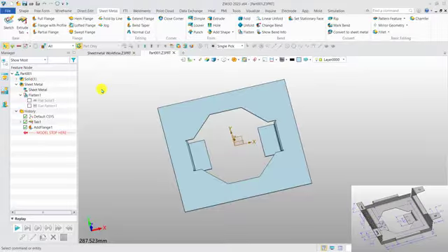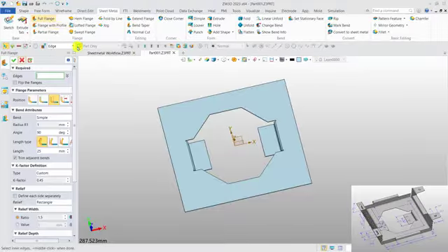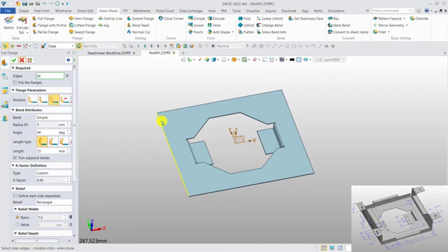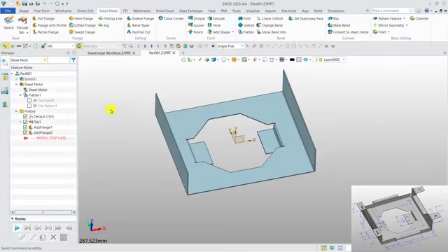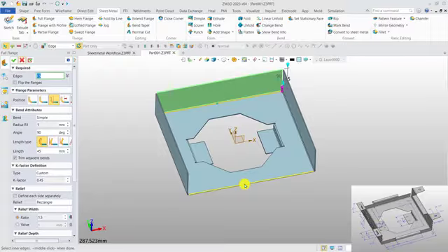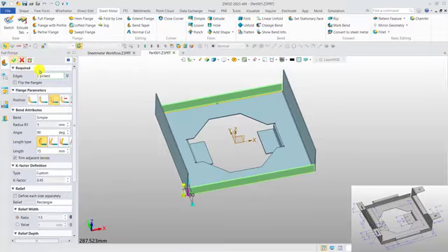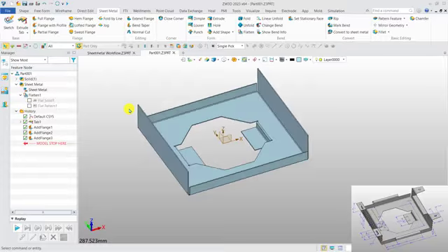Okay, and next we need to create another full flange for the side faces. Okay, so that is 2 and the length 45. Okay, and continue. We need to create another full flange. Another full flange. Also, the length will make it shorter, 15. Okay. And continue. We need to make